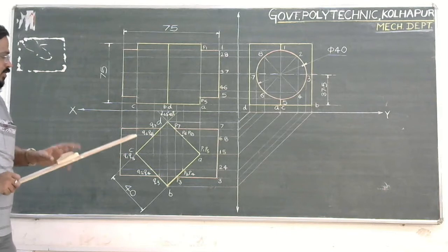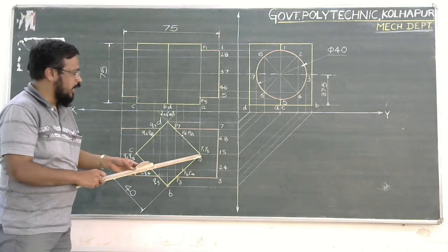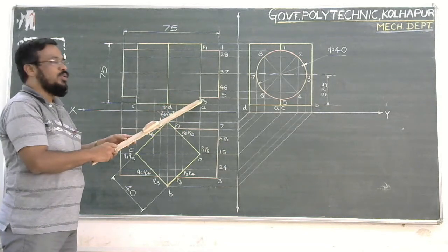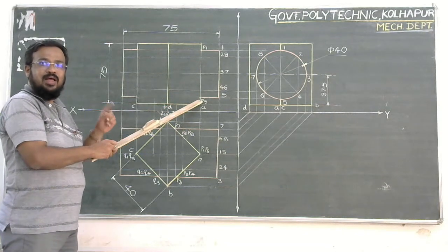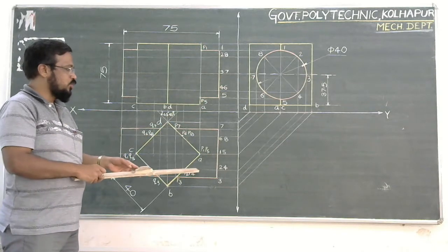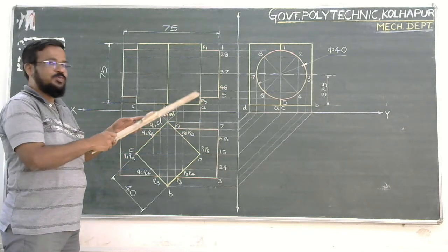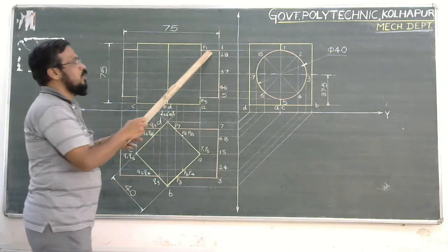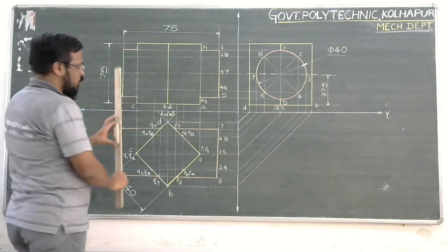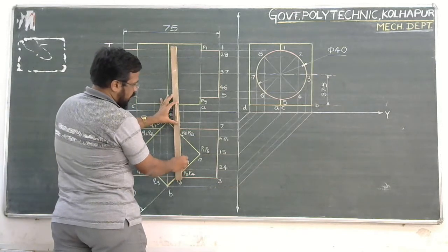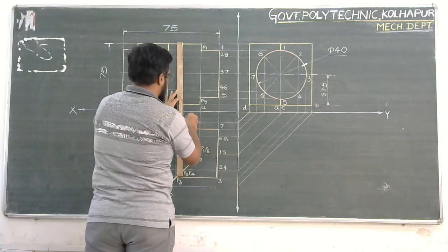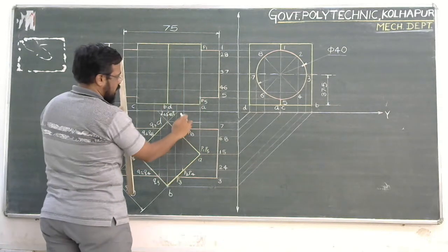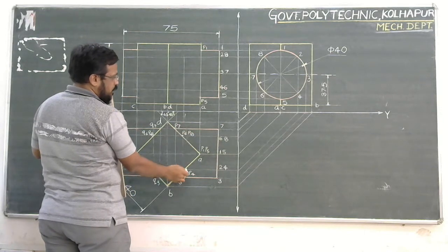With the same method, as we have transferred this P1, P2, and we have obtained the points P1 and P5 in the front view by getting the intersecting point, which is obtained by projectors from top view, which are moving upwards and transferring the horizontal locus in the side view. So similarly, P2, P4, P6, P8, these points, if those are being transferred into the front view, see, P6, P8, and P2 and P4.